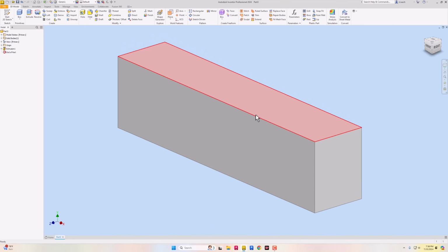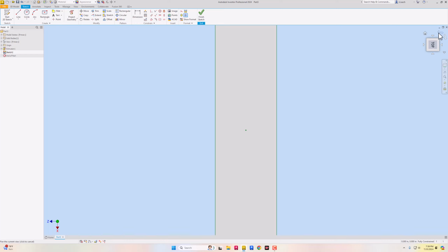So I know you're like, okay, what are we doing here? But I'm basically taking a big block as our starting point, and then we're going to chisel away what we don't need and do all that kind of stuff. But what I want to do is draw the circle on top and extrude that up. So I'm going to start my 2D sketch on this top plane. I want to rotate it to the left here.